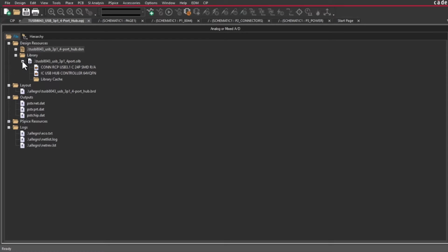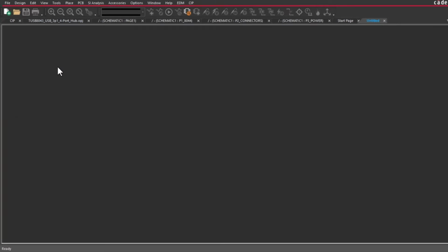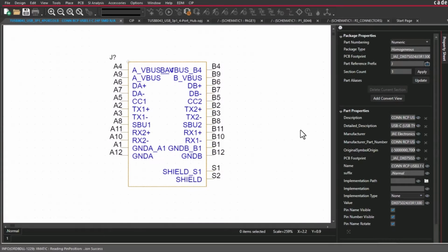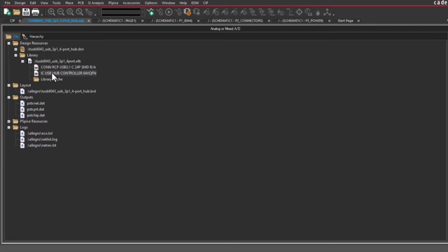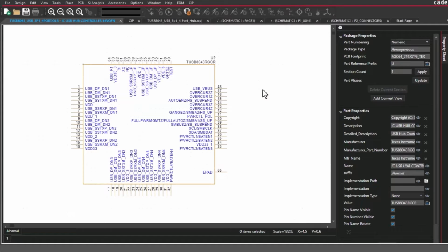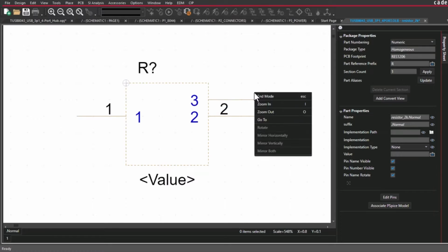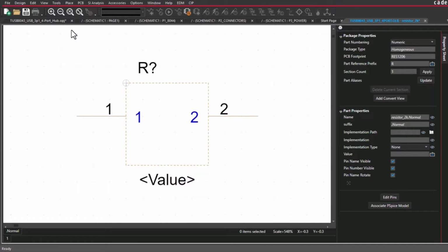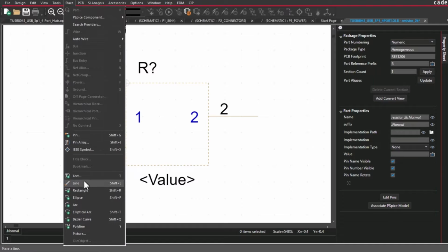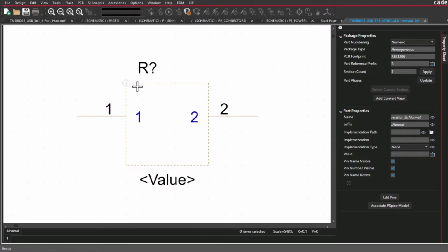Okay, since we're talking about components and parts, the next phase would be modeling those components in your design software. All right, so once you have your part selected, you need to create files that model the various domains of any particular device. For instance, let's break this down. You have the schematic symbol, which represents the high-level functionality of that part within your overall design.